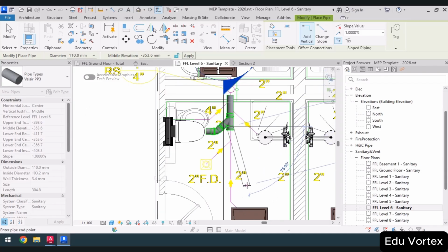If you want to change the size of the 2 inch or 50 millimeter fitting directly from this section, you can simply enter the size here, because we want to use a one-way conversion. So we will draw the fitting with the same size and move forward. For now, you don't need to change the height as it automatically detects the height from the pipe itself.